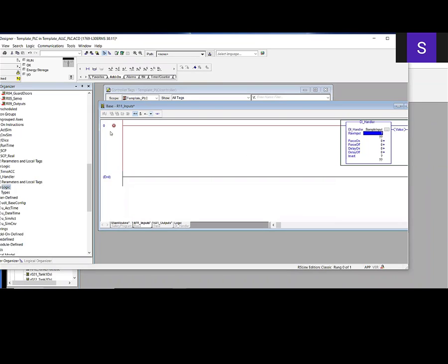And so all they need to do as part of their template is copy this and put all the physical inputs that they want to use. Again, because it's Allen Bradley, they would probably alias them to physical inputs, and they would have the name of something like cylinder extended procs. Cylinder extended procs alias to a physical input, and then pass out input dot value. And that's the way their template would work.